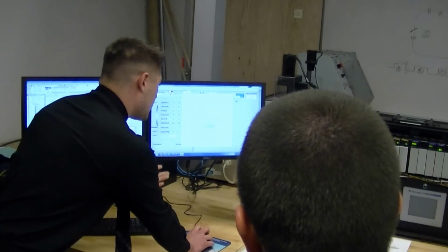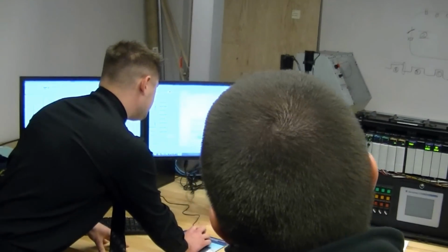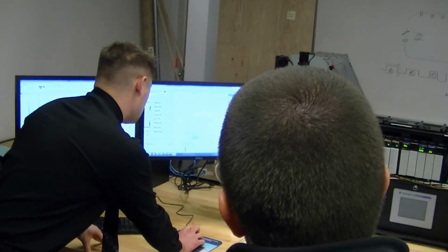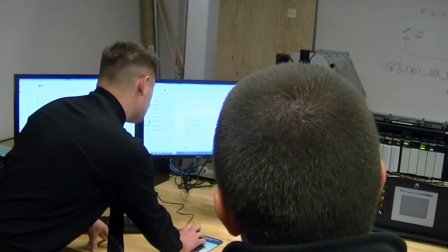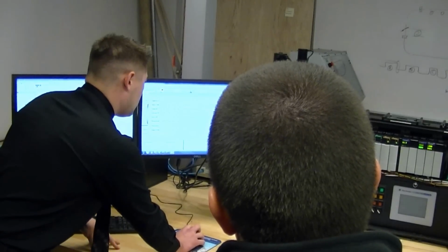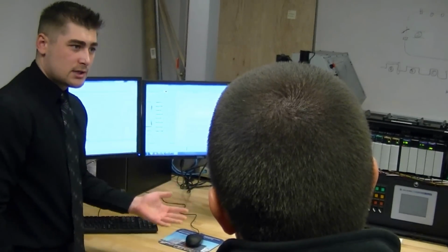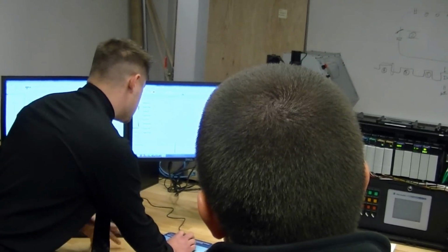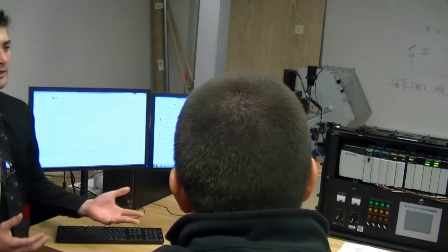Segment 3, we're going to ramp up to 100 degrees. And then finally, we'll soak at 100 degrees for 5 minutes. We'll do 2 for the sake of time. And then the user can also pick how long the cooling segment will be in this situation. So we'll make this, I guess, 3 minutes for the sake of demonstration. And again, it's very adaptable for the user.